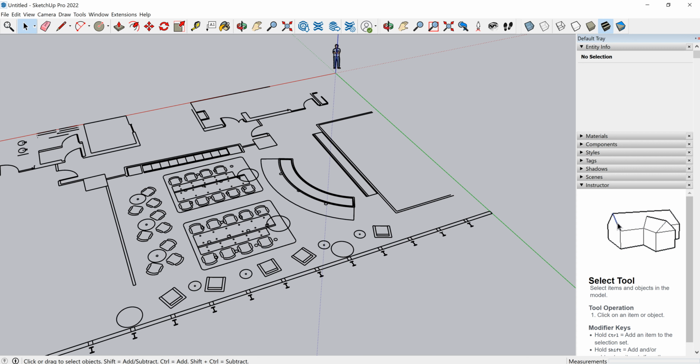So I'm going to be really quick with this exercise. I am always going to start a SketchUp model, probably either building up the floor first or the walls. And in this case, I want to do the walls, only because there's not a lot, but enough that I pretty much want to build them, and then I immediately want to turn them into groups. And that's probably the biggest tip I have for SketchUp and drawing in SketchUp: you want to make sure whatever category or object you are building, at the end of it, when it's drawn correctly in your mind and what you know, you're going to turn it into a group.